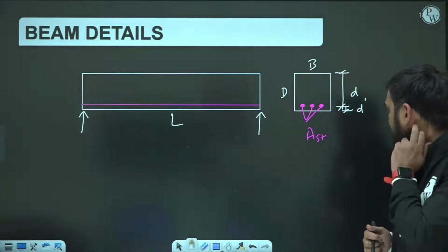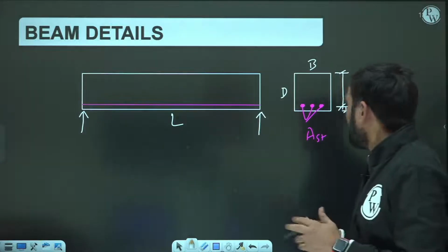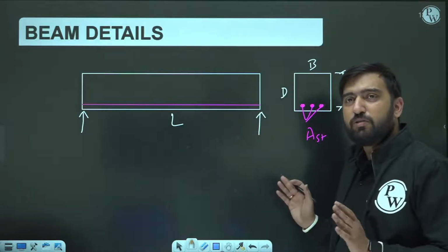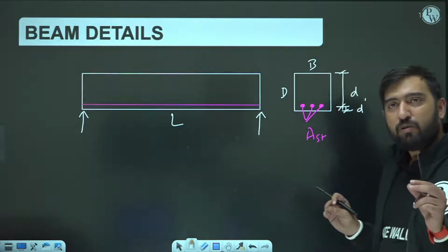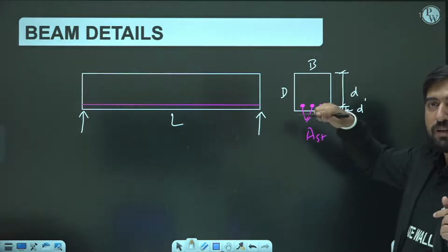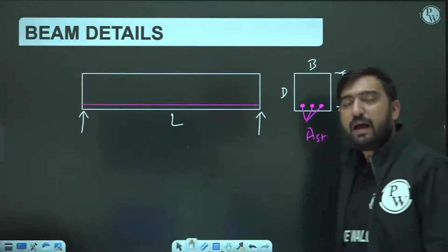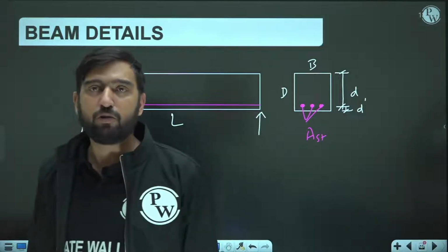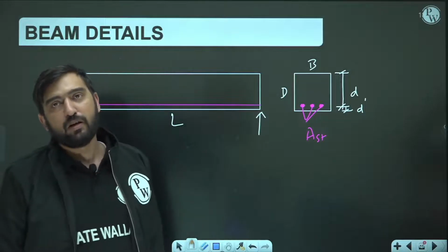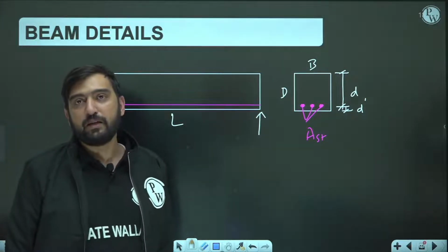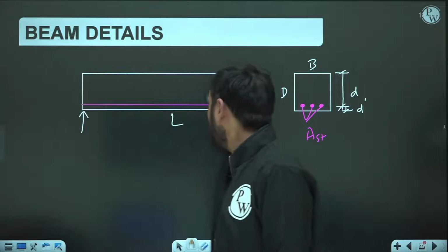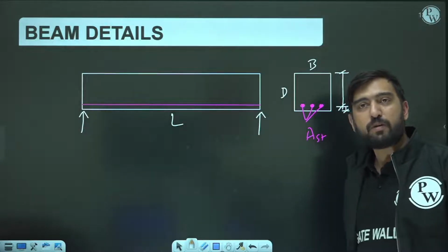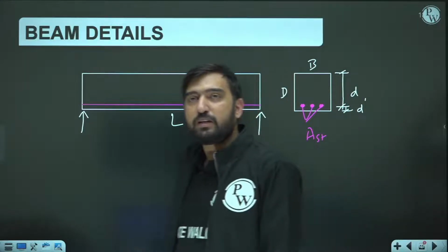Okay, now dear, catching would be easier for you now, because all the technical stuff, all the procedure you know. All you need to do is just change that parabolic rectangular portion into the linear one, and other than that, one more thing you have to keep in your mind, that this time there is no factor for load, only there is a factor for material. Okay, so yes, I will also introduce soon what all are the partial factor of safety here. I hope you remember the partial factor of safety of concrete and steel in LSM.